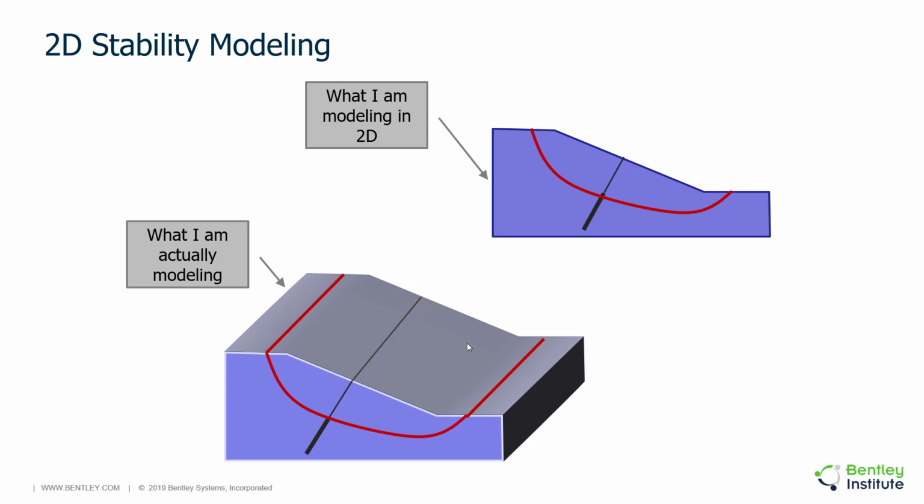friction. So that is why it is a little conservative in 2D analysis, because you're not really considering the ends and the frictional resistance of the ends. And your anchor, of course, becomes a steel plate in 3D. Ideally, that's not the case. Anchors are point loads. So we scale it back and we artificially reduce the strength of anchors in a 2D analysis, but fundamentally, according to the theory, you're representing a plate in the 3rd dimension.